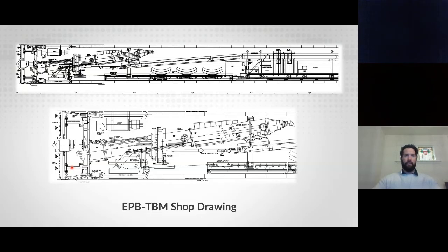And the surplus excavated material plus these additives come up with a toothpaste-like consistency, which allows the contractor to effectively maintain pressure at the face of the machine by using earth pressure balance. And as the material gets mixed here, the screw conveyor that we can see here will screw the material from the mixing chamber and take it out ultimately to the muck carts and ultimately dispose off site.